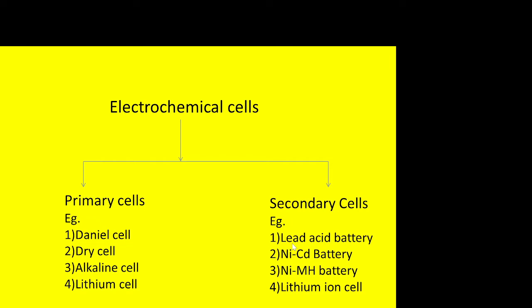It is because the positive electrode usually gets eroded, so the plate area of the positive plate decreases with time. Also, lead sulfate in the amorphous form is the active material, and has a tendency to convert into the more stable crystalline form, which is not an active material.